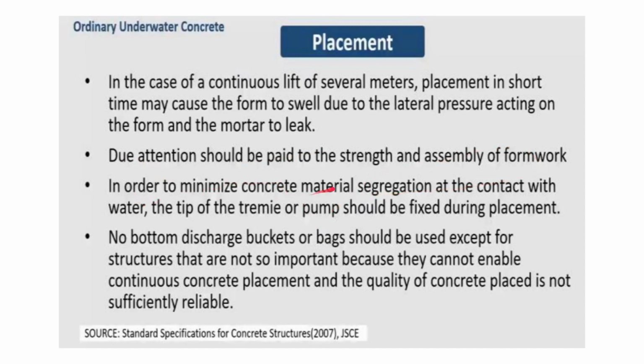In order to minimize concrete material segregation at the contact with water, the tip of the tremie or pump should be fixed during placement. Okay, so there should be no contact with water at the tip of the concrete. Okay, so therefore the tip should be inserted inside the concrete fill.